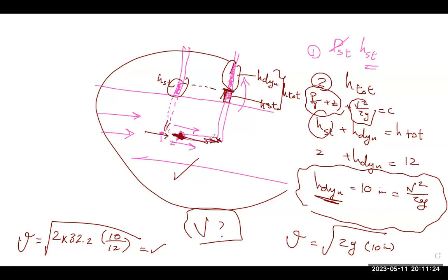Due to both. The first one goes inside with the regular static pressure, so it rises the distance for the static. And due to the stagnation, all the kinetic energy due to this movement is also converted to height. So instead of a small distance like the first pipe, you will find a large distance, reflecting both static and dynamic.